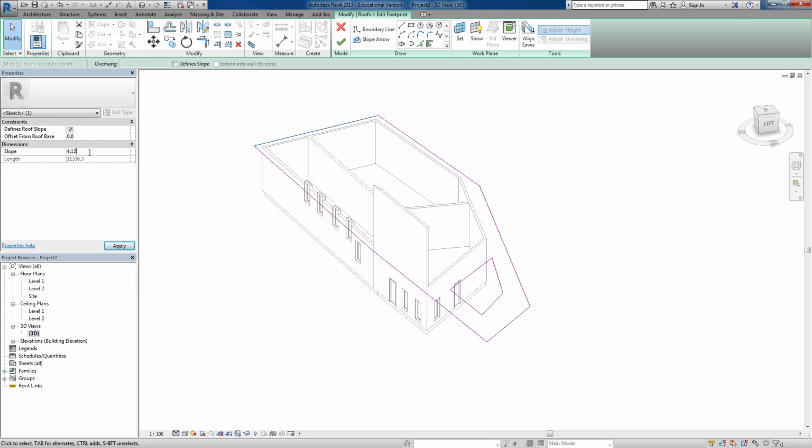I don't know if you guys have heard about these typical slope roof dimensions, like 4 to 12, 6 to 12, 8 to 12, based on imperial measurements, meaning that if you have a foot tall or 12 inches tall or 12 inches wide roof, and you want the slope to go up 4 inches through that 12, it's a 4 to 12, and you can put that in. It will just translate that into a degree or an angle, and then we'll put it in. So for now, I'm just going to be metric. I'll just put in the 20 degrees for that one single line.